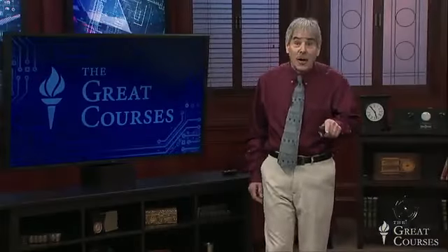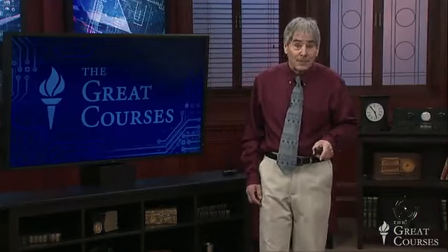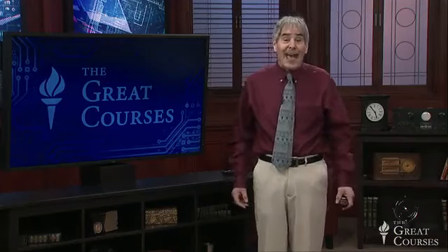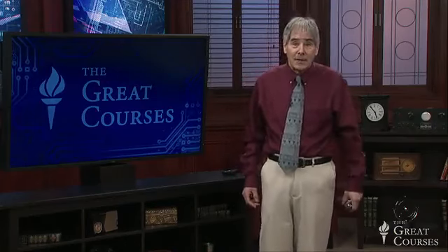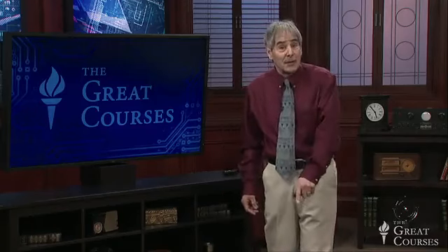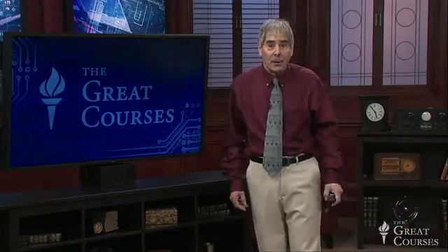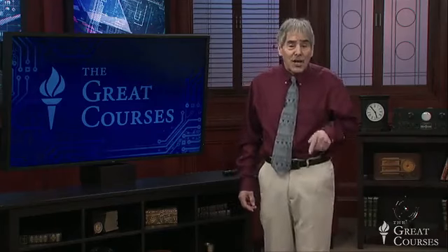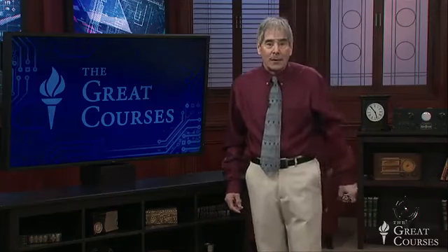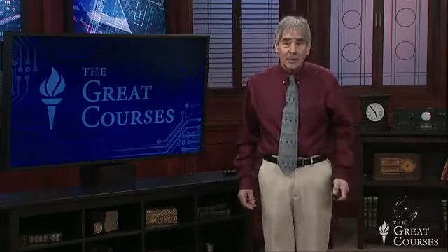I mentioned earlier that op amps are called op amps partly because they do mathematical operations. Well, here's an op amp doing a mathematical operation. It's adding two voltages, and the output is basically the sum. If you don't like it to be the negative sum, put a unity gain inverter on the back of it, just like we did with the gain of 3 amplifier before. If you don't want it to change the voltage, but actually simply add them, make R feedback equal to R in, and you will get an output voltage whose magnitude is the sum of the input voltages.